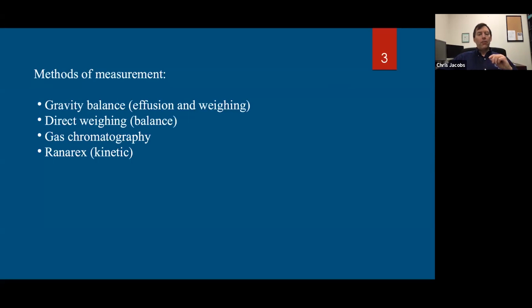I will mention most chromatographs are C6 plus chromatographs. So the hexanes and heavier gases are pulled out as one. You're not going to get a composition of those heavier components. However, in most natural gas, the C6 plus, the hexanes and heavier, are less than 1%. So it really is not going to be a significant amount.